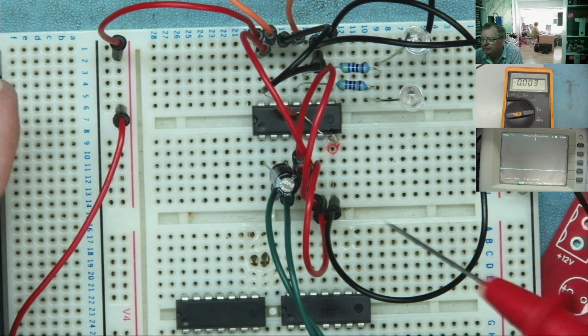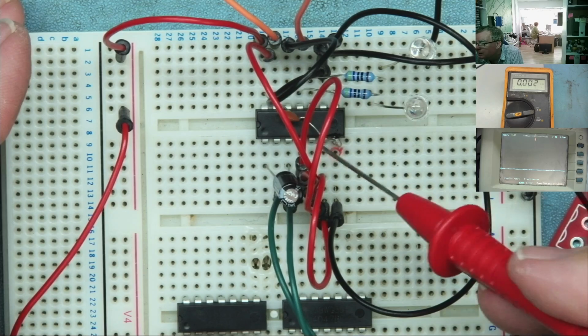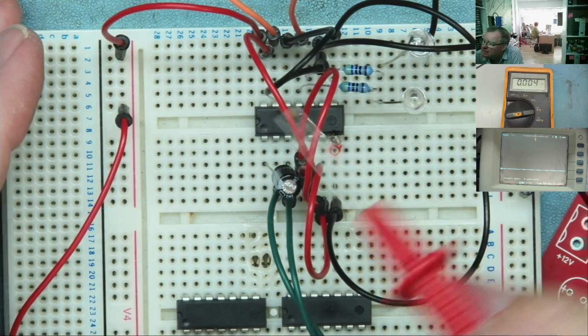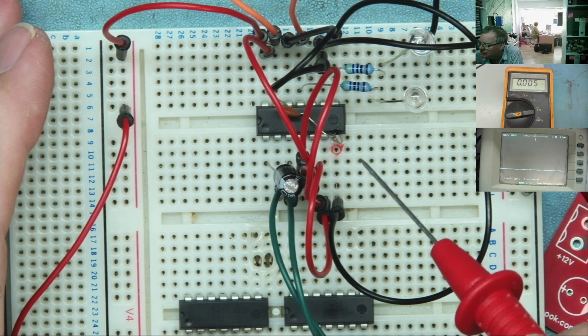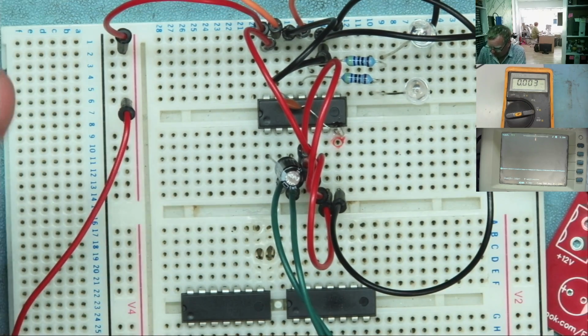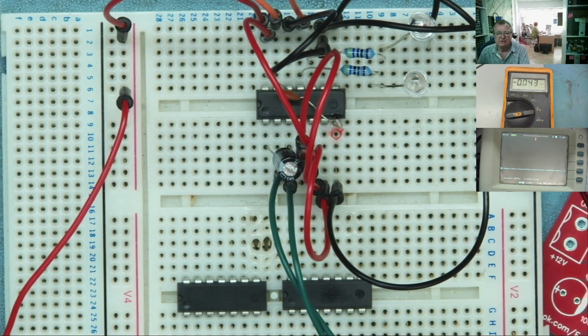Well, this proved rather tricky, so what I've done is I've actually soldered the capacitor to the ground pin, and then I could get across to the power pin, so that's mounted directly across the chip. If it's going to work, that's the best place for it. Okay, I've connected the oscilloscope back up again now, so let's see what happens when we power this up.